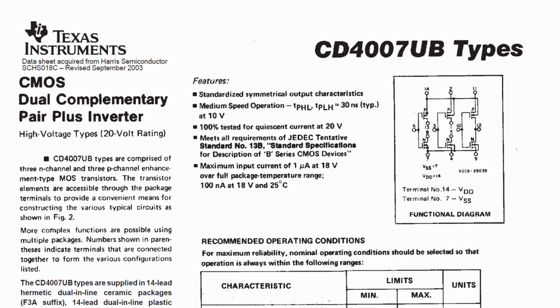And when we were designing it, we realized we needed a clock. We needed to generate a clock signal that would just go up and down, up and down. And at the time, a chip that I had lying around on my workbench was the 4007 chip. And it's such a versatile chip. This thing is basically a bunch of balanced NMOS and PMOS MOSFETs. But what I did with the chip is I essentially configured that 4007 chip to behave like three CMOS inverters. That's all we did. And then we took those CMOS inverters and plugged them in a certain way so that we can get a little bit of a clock pulse. And if you're interested in how to do that, make sure you go watch episode 13, I think it was.